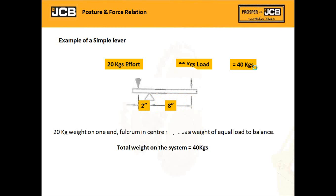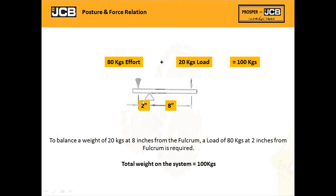But now see what happens when the fulcrum is shifted towards the back side. That means here we have a 2-inch distance and here we have an 8-inch distance. The moment the lever fulcrum comes over here, if we have to balance this 20 kg load, it can only be done when we put an 80 kg load over here. So the moment the fulcrum gets shifted and we have to balance this 20 kg load, we have to place an 80 kg weight over here, or an 80 kg effort. That means the overall effort which is coming on the system is 100 kgs.